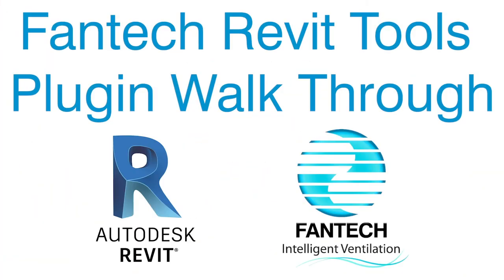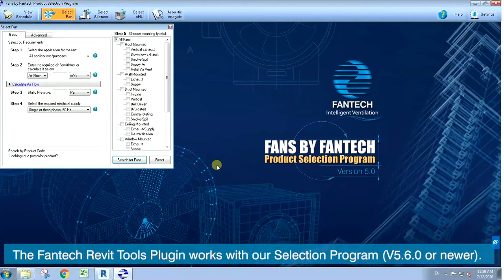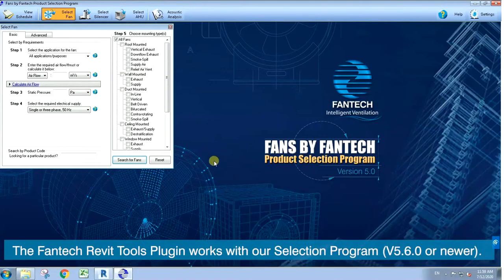This is a video walkthrough for the new Fantech Revit Tools plugin for Revit. Once you have downloaded the plugin installer and installed it on your machine, the plugin also requires an updated version of the Fans by Fantech Selection Program. You need version 5.6.0 or newer.